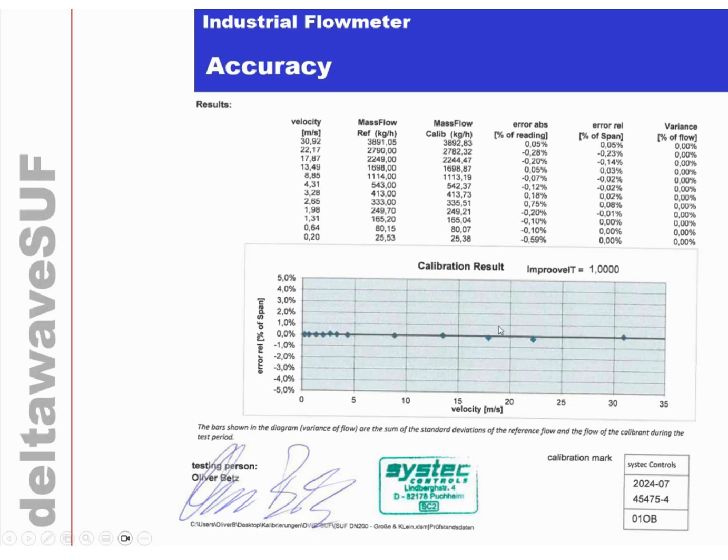We are just rethinking our test bed if we replace our calibrated turbines. These are calibrated by the highest authority, by the PTB in Germany, and we are thinking about replacing them now by the ultrasonic flow meters because the span is just huge and they just fit the zero line. So with a small calibration or linearization at that point, we can come to a just perfect accuracy here. So very impressive.